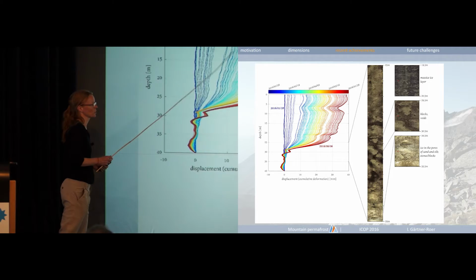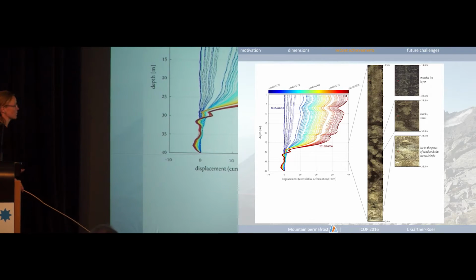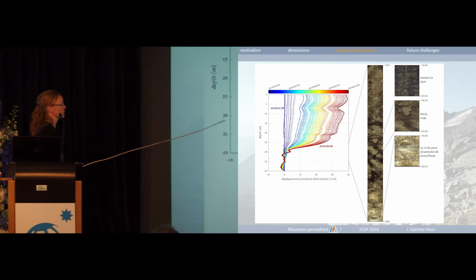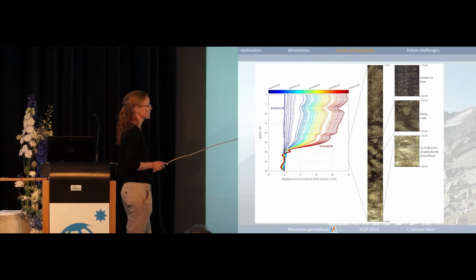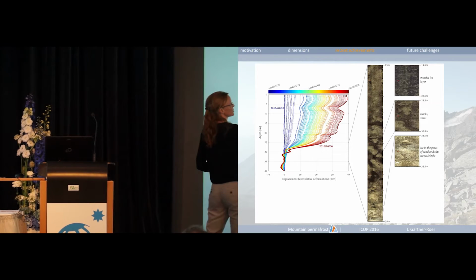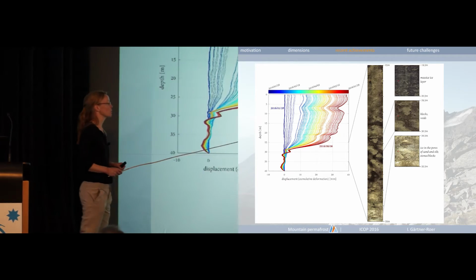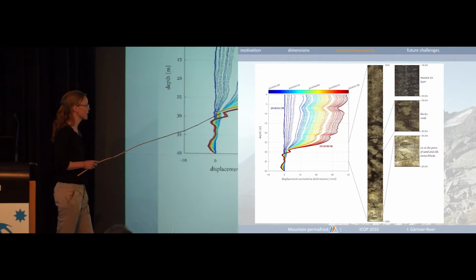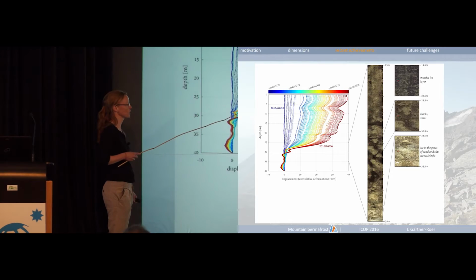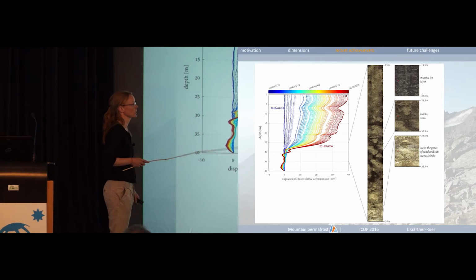And this is also now the very first data we can show you. So it started with the filling in the sand in the borehole in January, and up to now, up to 1st of June, this is a wrong date here, we could measure nearly 4 centimeters of movement. Main part of the movement is occurring here in the shear horizon, as you can nicely see.